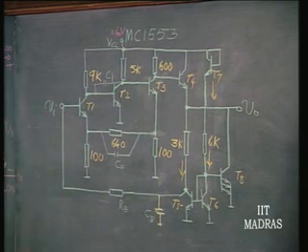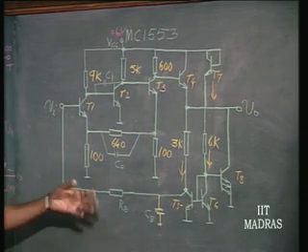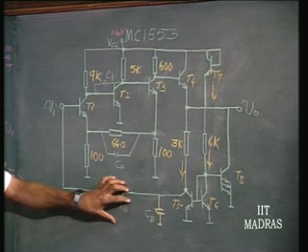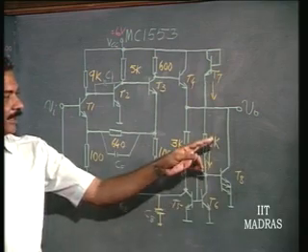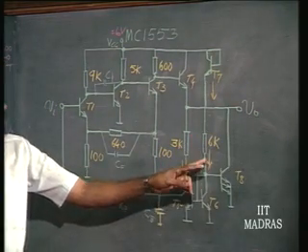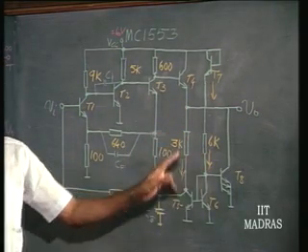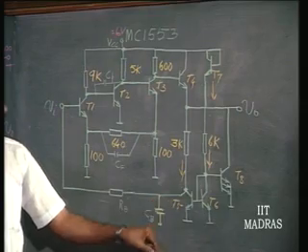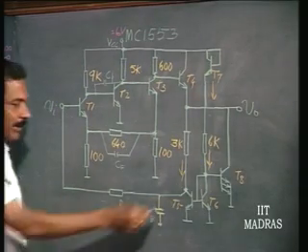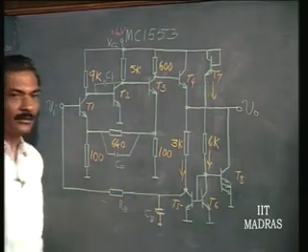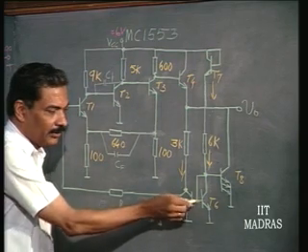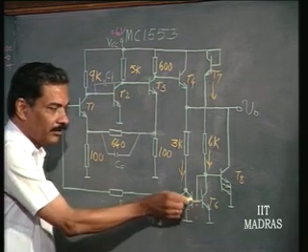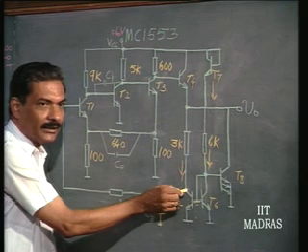So, in which case, as far as the AC picture is concerned, this will go out of picture. This is going to be pretty high resistance. Okay. So, this will go out of picture. This current is essentially the same as this current. So, if this is 0.8 milliampere, this also is 0.8 milliamperes, and therefore, what is the potential at this point? The base is at 0.6, let us suppose, from ground. What will be the potential of the collector here?